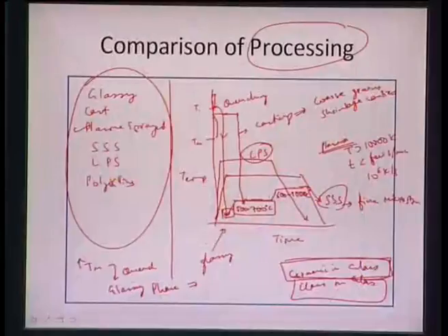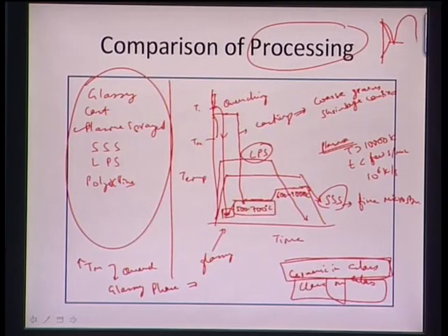Once we have cooled it, depending on the way we are cooling it, we can again retain the glassy phase itself. Once we have much more of a network former in the liquid regime, we can retain the glassy structure itself, once we have two liquids which are forming at much higher temperatures. So, for glass in glass, we need a phase diagram where we can see two regimes forming, liquid 1 and liquid 2, at very high temperature. So, we have immiscible liquids at high temperatures.